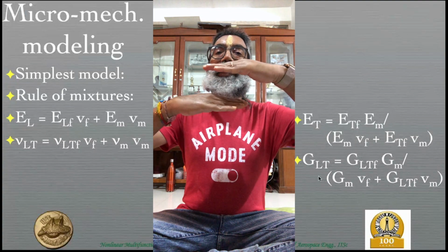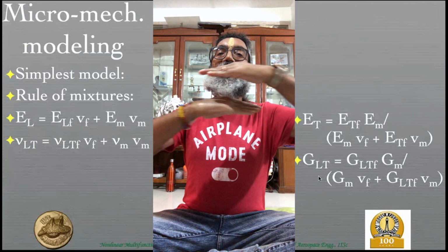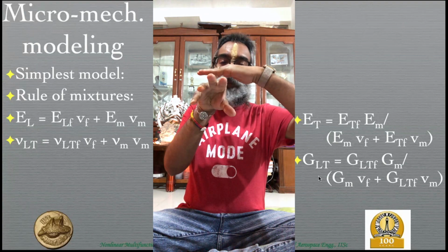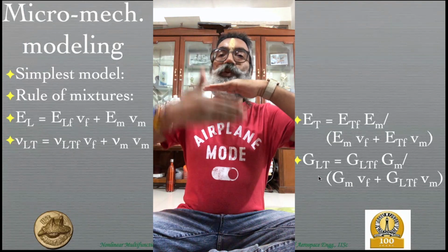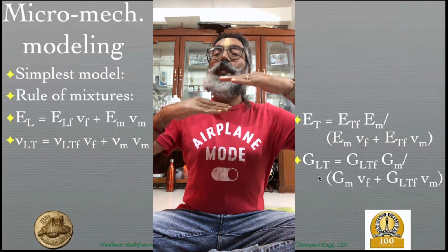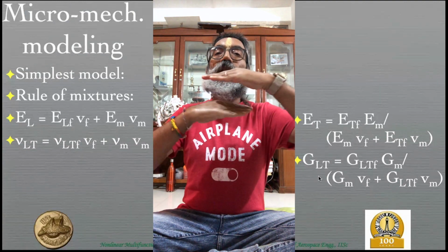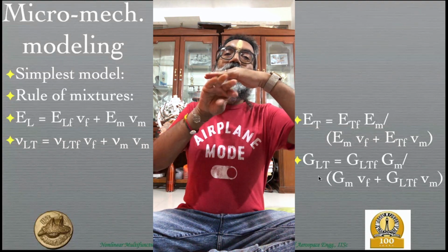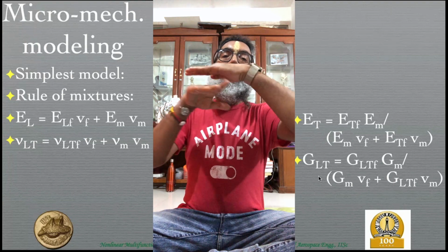Now what I'm talking about is, you're applying a shear stress in this direction, measuring the change in the right angle. It's very easy to see, even though you have fiber reinforcement, because of the direction of the fiber reinforcement, it is this particular behavior in the transverse plane, which is perpendicular to the fiber direction, that is going to be matrix dominated. So whether it is the Poisson's ratio nu TT prime or the GTT prime, they are going to be dominated by the matrix, because even though the fiber is present, it hardly plays a role. It will just move along with the matrix. As the matrix deforms, the fiber will just move.